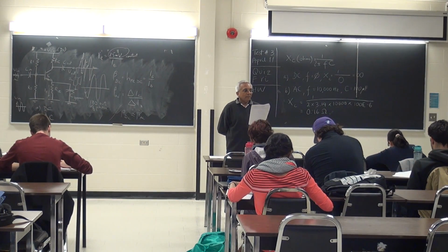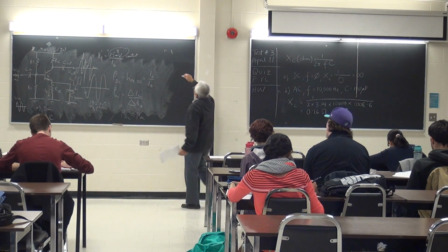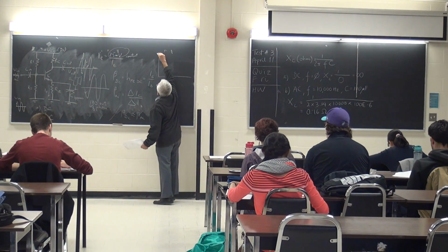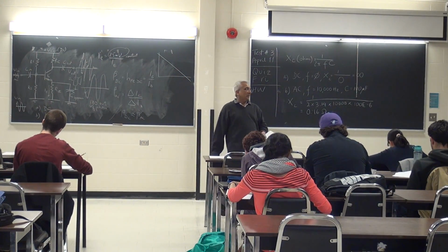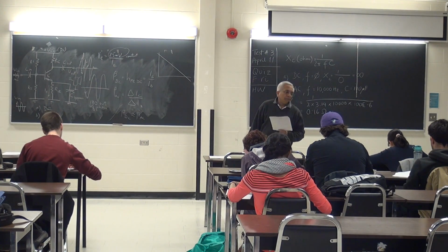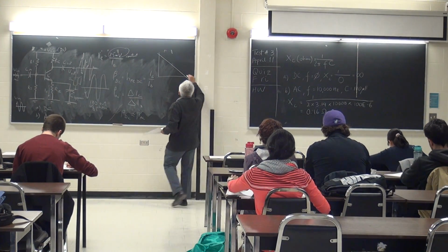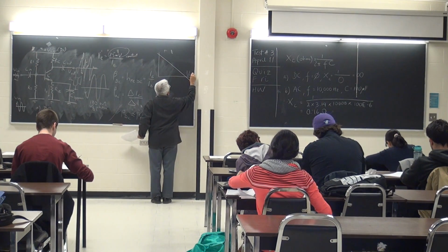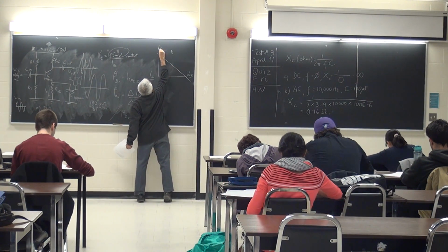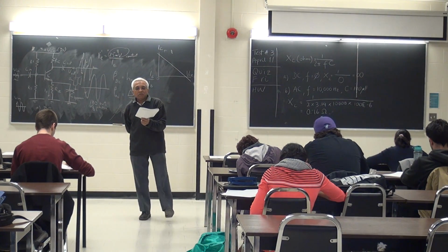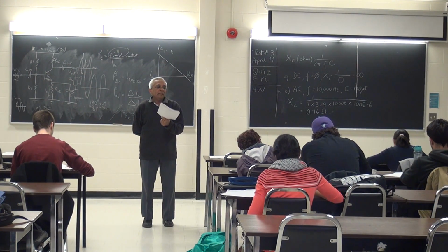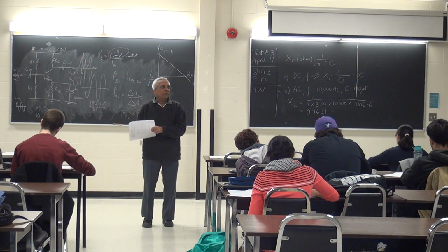So, first thing is draw your load line. X-axis, VCE. Y-axis, IC. First calculation or information, cutoff.